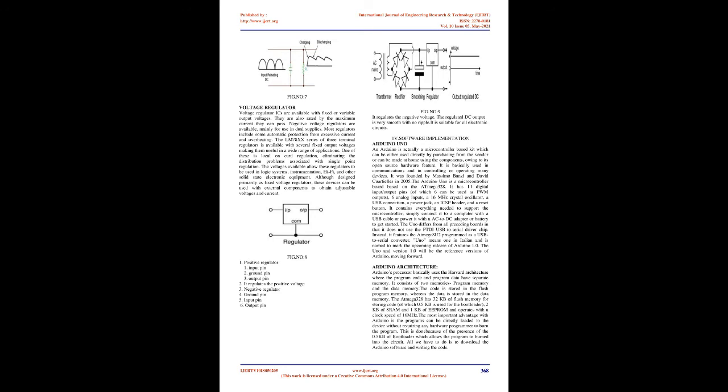The LM78XX series of 3-terminal regulators is available with several fixed output voltages, making them useful in a wide range of applications. One of these is local on-card regulation, eliminating the distribution problems associated with single-point regulation.